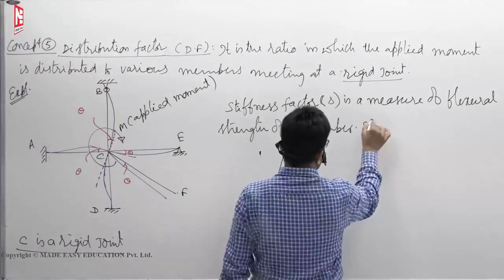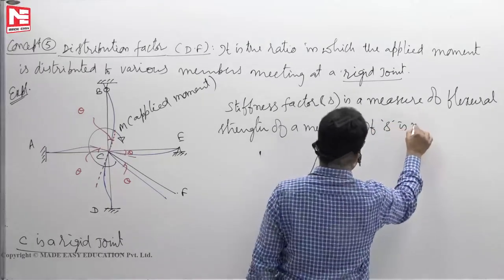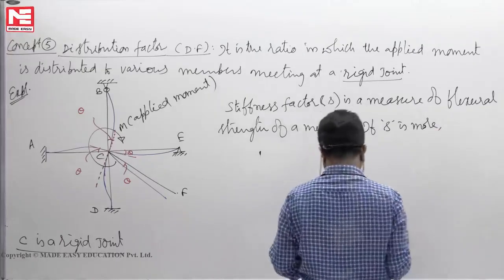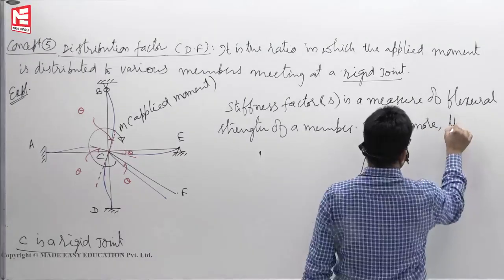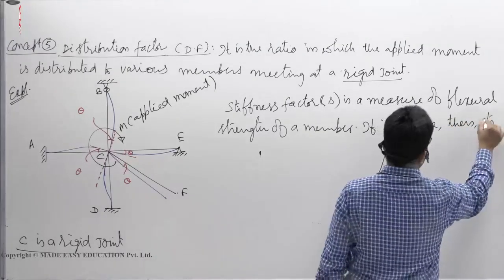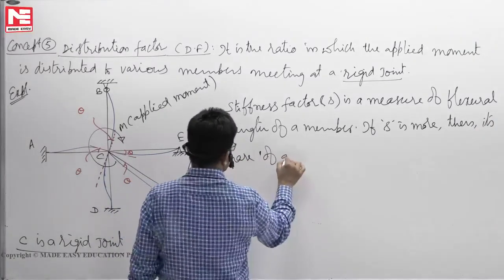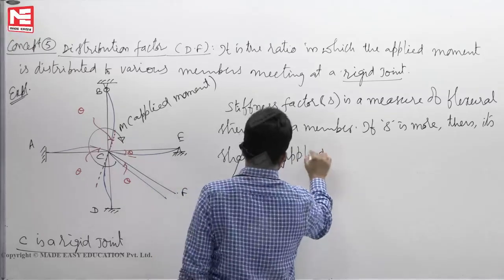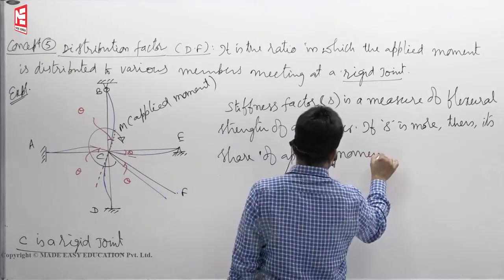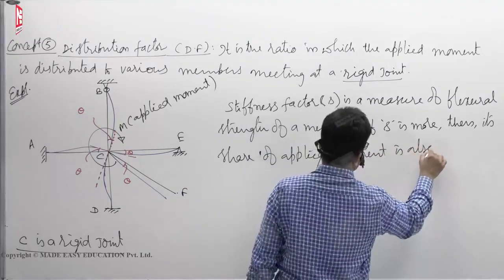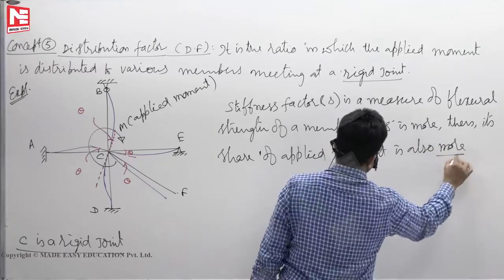If S is more, stiffness factor is more, then its share of applied moment is also more.